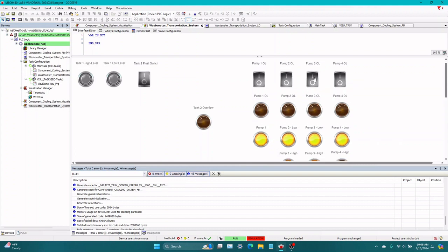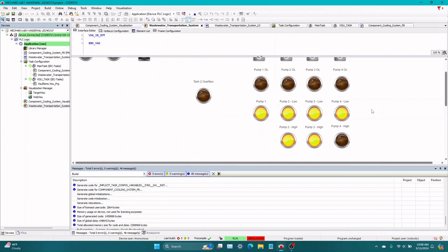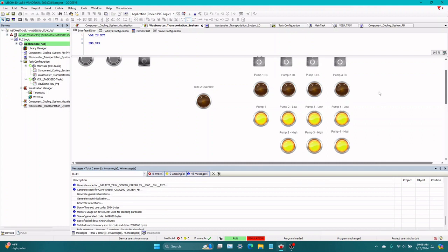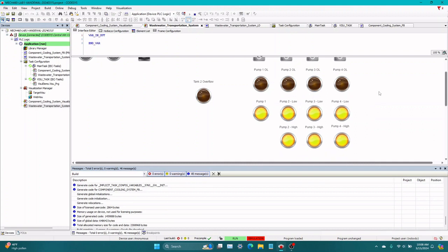So that's the functionality that I added. And of course, if they're all going, there's no extra pump to run. So if they're all going and an overload turns on, it will just simply shut off. That's not ideal, but there's no other way we could get past that without adding another pump.